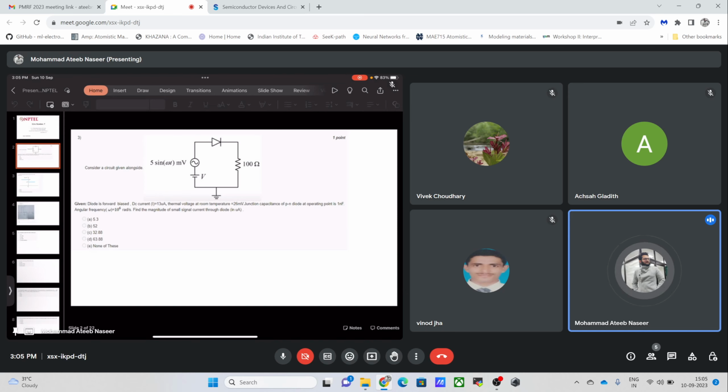It's not a hetero material, because hetero materials can also be used for the diode, or PN junction functioning. But here, for the basic cases, we start with the homo junctions. That is, on the P side and on the N side we have the same material, so we will have the same electron affinity for the P side and the N side.